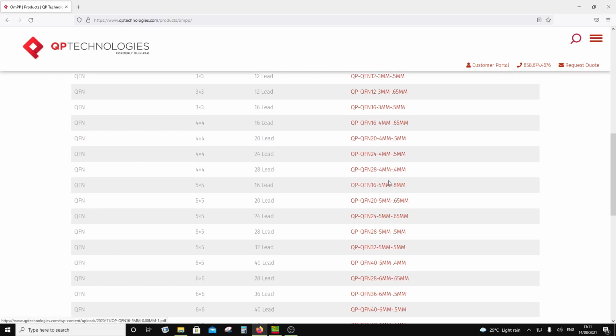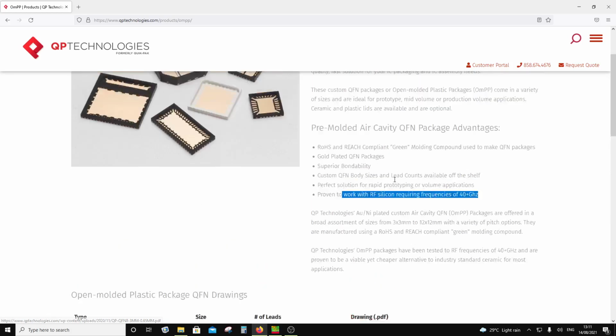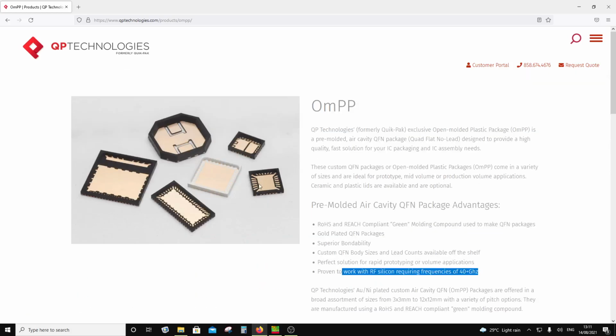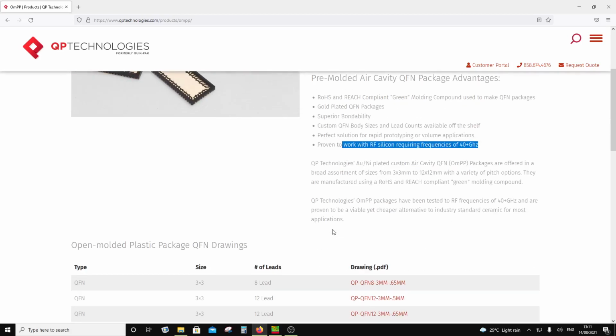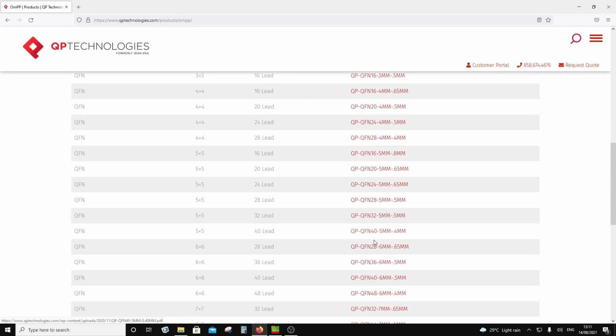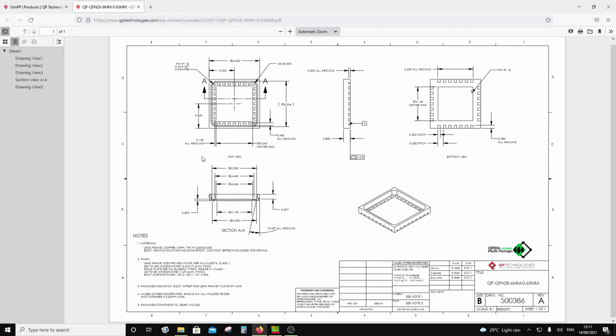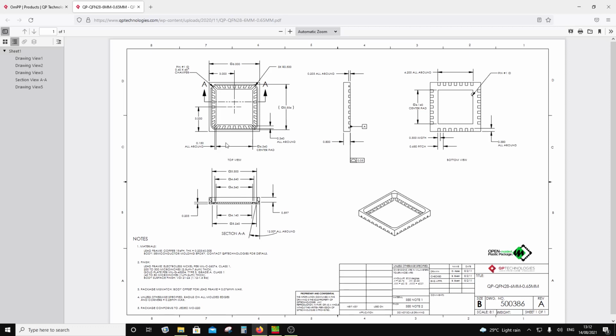So let's say I want a 5 millimeter by 5 millimeter, right? And I want the interior pedestal. So call the interior pedestal where your chip is gonna sit. So I want that one to be 4 by 4 mm. So if I choose the outer diameter to be let's say 6, and then it is 0.65 as the borders, so probably I will have here 4.3. So you can see here this basically shows you.